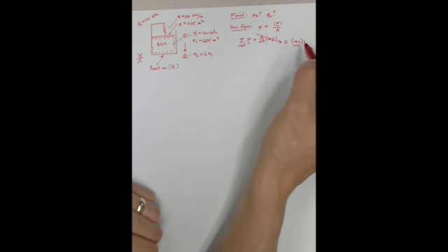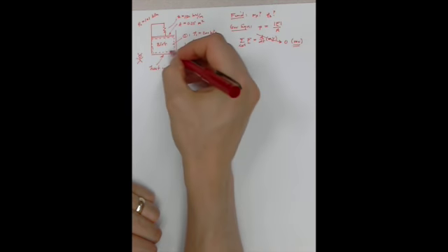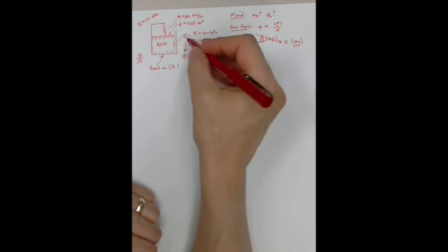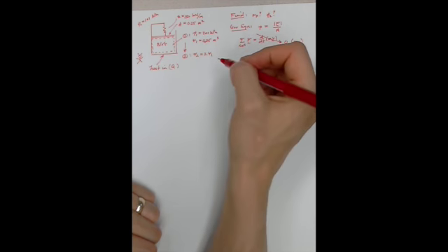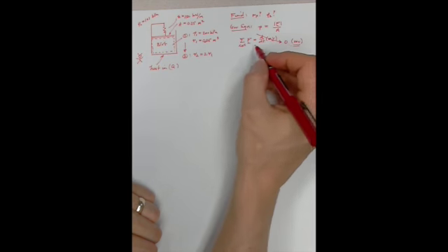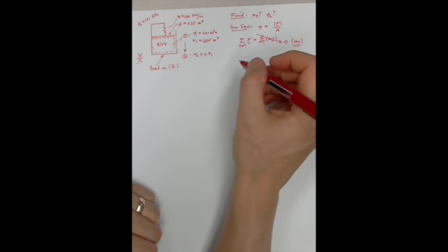So a reversible process is simply a continuous set of equilibrium states. So each one of these pressures and volumes in between 1 and 2, we're going to reach in a balanced way, not due to a force imbalance.